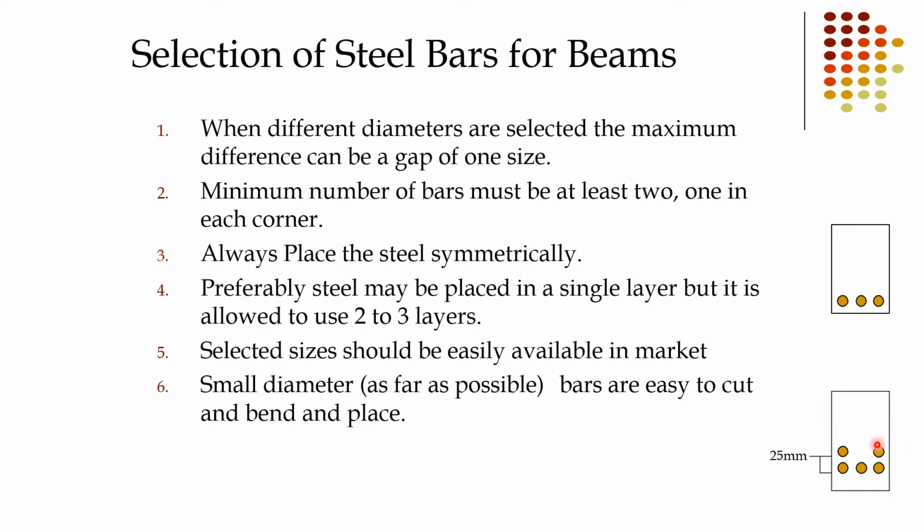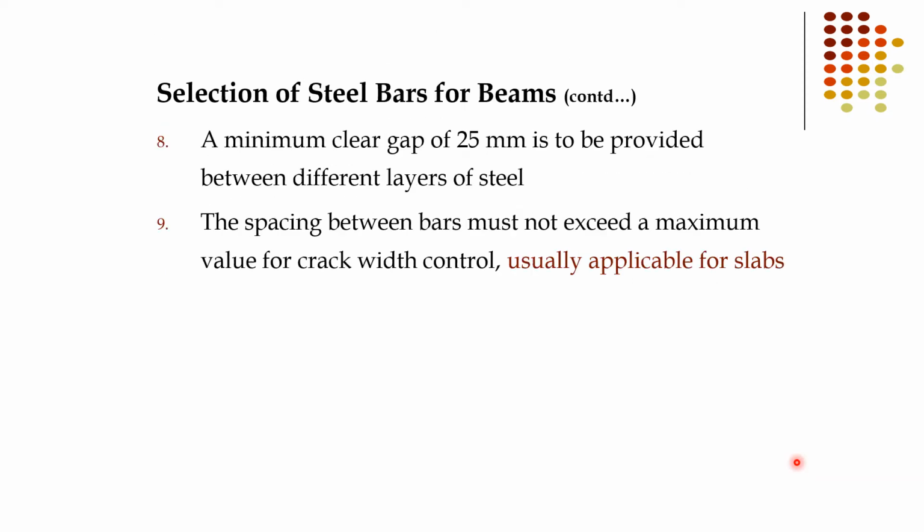Even different two layers, 25 millimeter should be provided. The spacing between bars must not exceed a maximum value for crack width control, usually applicable for slabs. When we go for slabs, then we will discuss what the maximum spacing of bars provided in the concrete is.